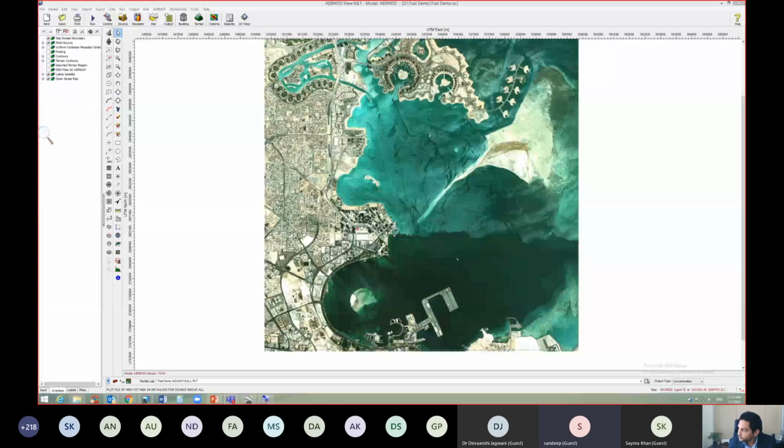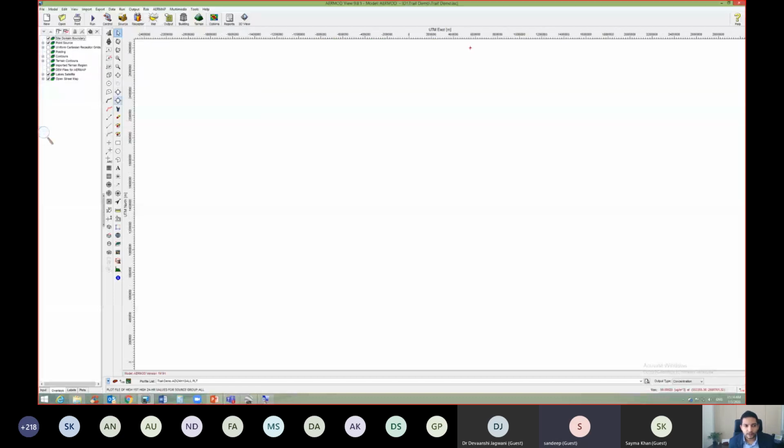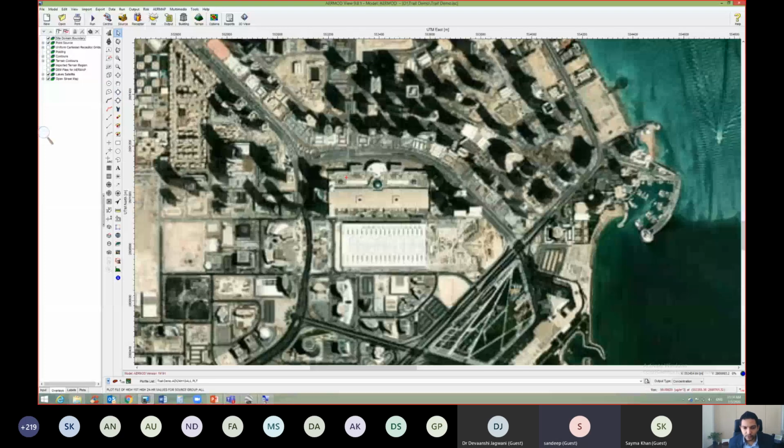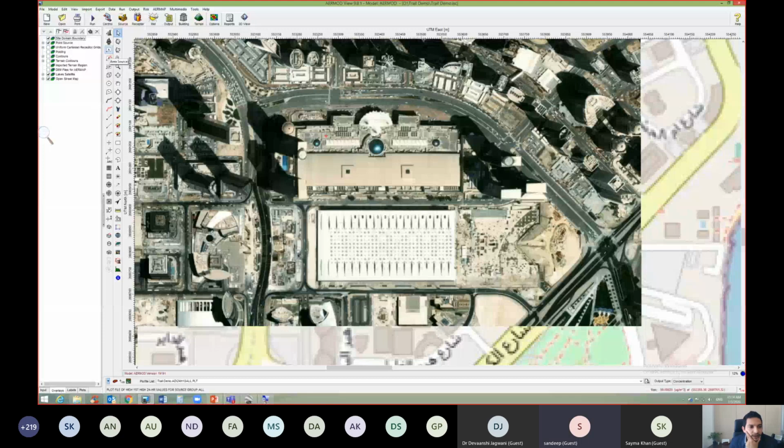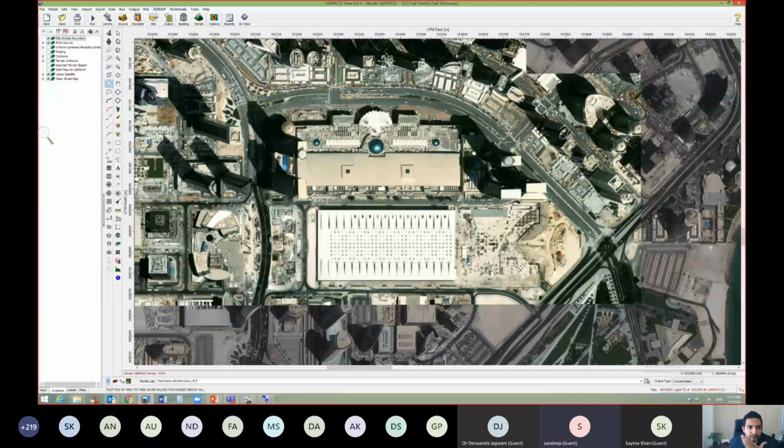So if it is an area source like a pond or a tank or a lagoon, like a wastewater treatment plant, in that case, how will we be calculating all these parameters? What we can do is create an area source. Here we can see this is an area source, and this is a circular area source. If it is a pond, we can create a circular area source like this, or if the pond is not circular and is an irregular shape, we can also create a polygon and define the source.